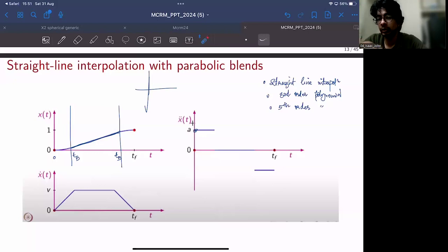But imagine if there were no safety mechanisms: if the torque is too high, the motor will burn off. So all these situations are to be avoided. If you command something that is not physically possible, it can lead to a lot of damage.